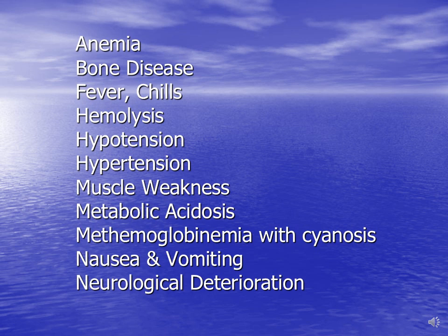So the question is, when patients exhibit signs and symptoms, how do you differentiate whether it's water related or something else? In a typical dialysis setting, in a centralized feed water system, there's a cascading effect with these kinds of symptoms. The person nearest the water treatment system, where the water first comes into the unit, would exhibit the symptoms, and then the next, and then the next, almost like a domino effect.